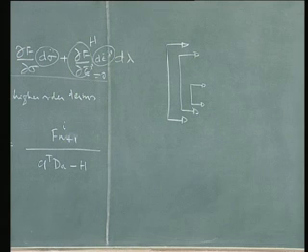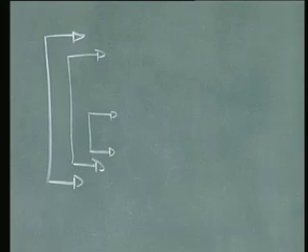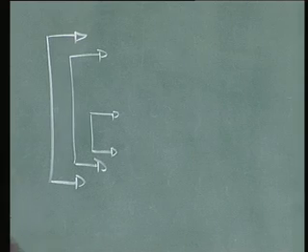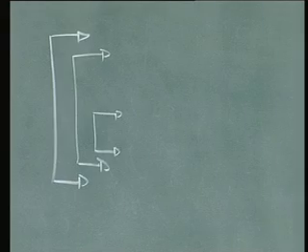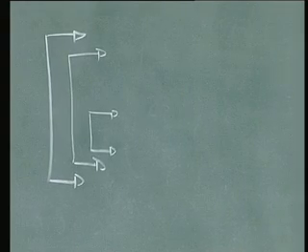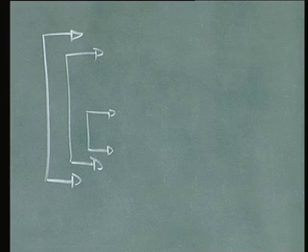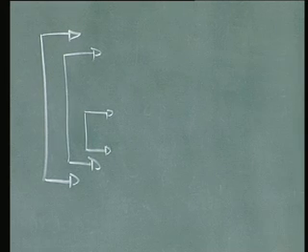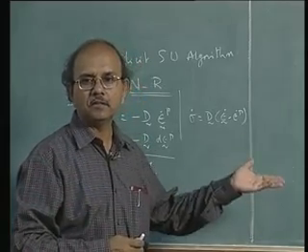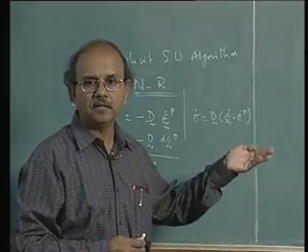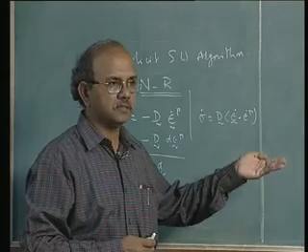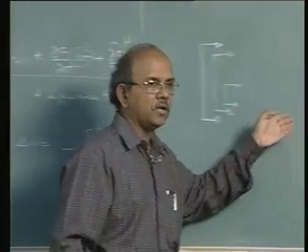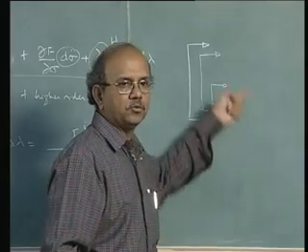Okay, my consistency condition is satisfied. So you have 3 different loops now. Okay, this is the typical implicit algorithm. Is that clear? So what you essentially do is to calculate delta lambda, calculate d sigma, calculate sigma, calculate epsilon bar p, and then see whether f n plus 1 at a particular iteration inside this loop is equal to 0. If not, go back and do this.